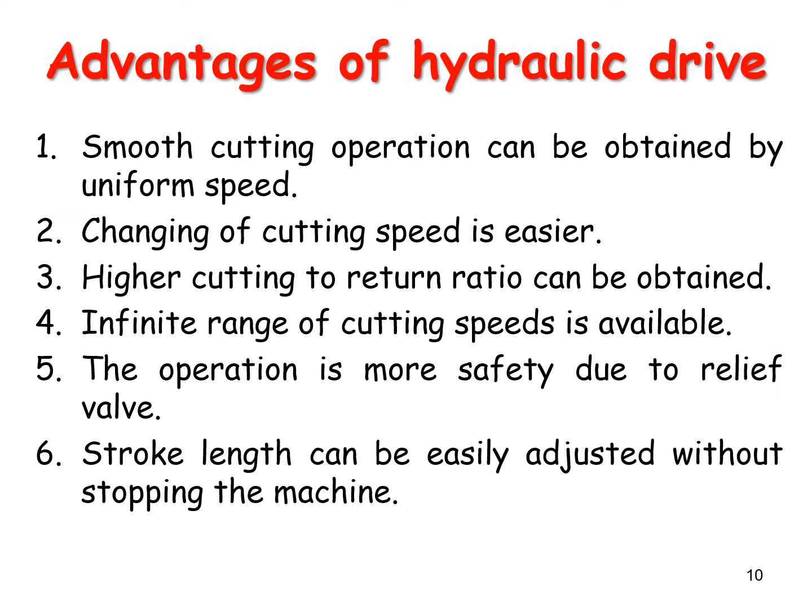Some of the advantages of the hydraulic drive: a smooth cutting operation can be obtained by uniform speed. Generally the hydraulic drive gives a smooth, silent cutting operation. The changing of cutting speed is easier. In case we want to modify the cutting speed, adjusting it is very easy. A higher cutting to return ratio can be obtained. An infinite range of cutting speeds is available.